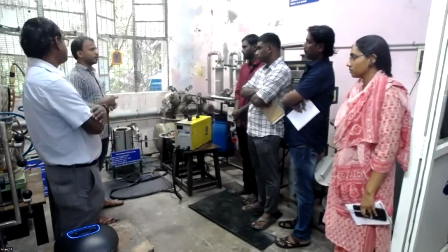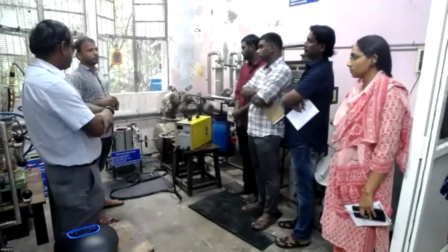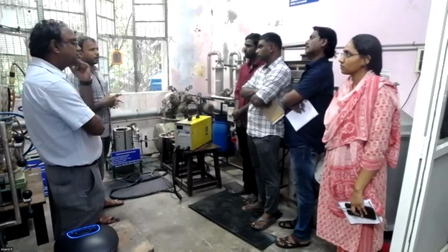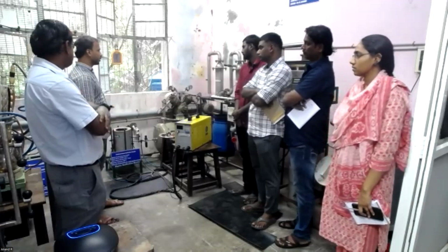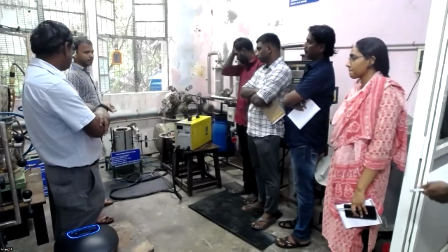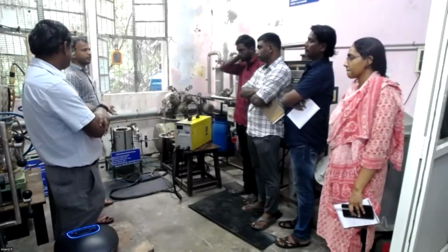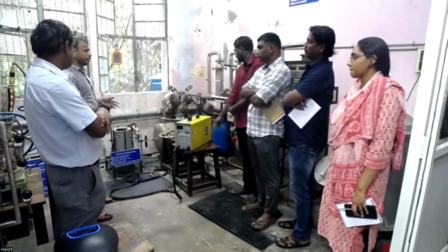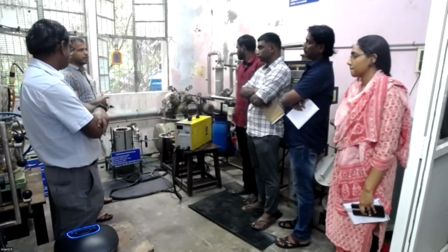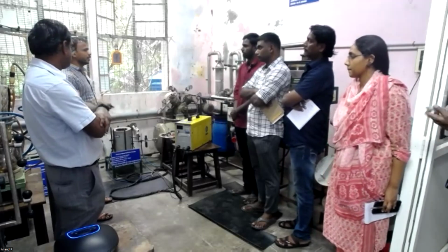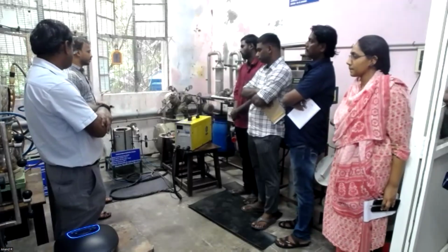For our case, conversion may go beyond 99%. If you put in 100 grams of solid waste, it will convert into 1 gram of solid residue. So that much complete degradation happens. If you go with pyrolysis or gasification, the solid residue may be 5 to 10%. But for this case, it will be very minimal. For incineration also, we will get around 6 to 7%. Some unburned material may be there, but here it won't exist.